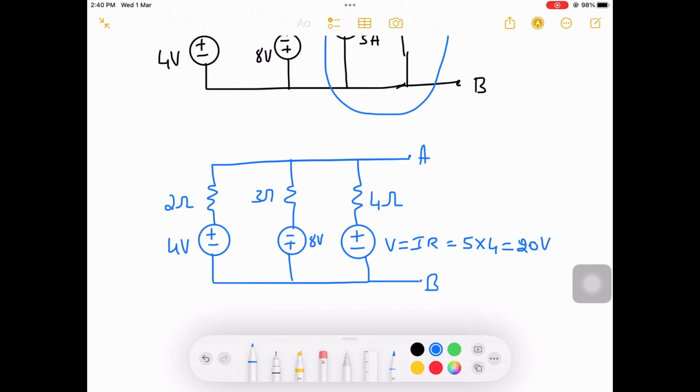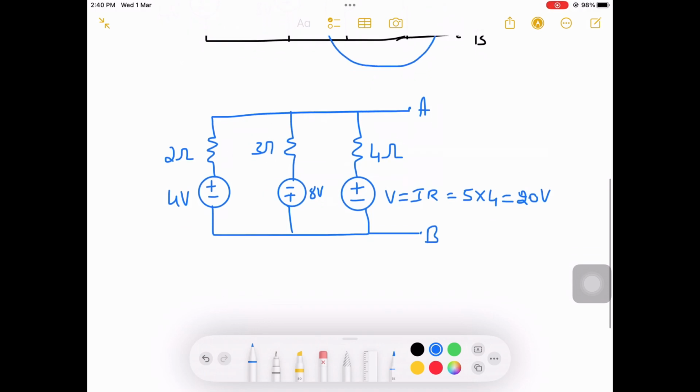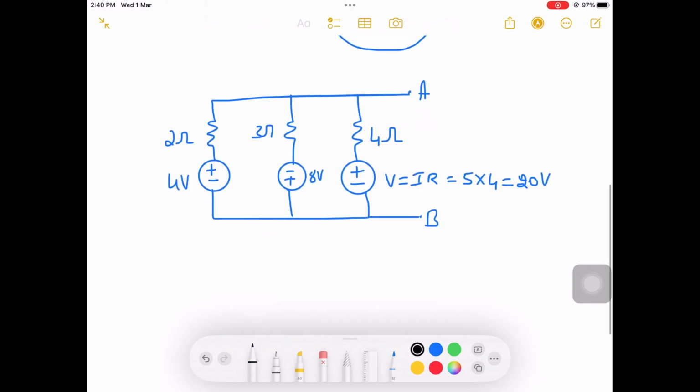So now there are 3 voltage sources I can add easily, right? Here Millman's theorem has a formula for finding that. The values given here are the impedance Z for the problem, whereas Millman's theorem requires the equation in terms of admittance. The equivalent voltage source can be represented using the equation in terms of admittance.